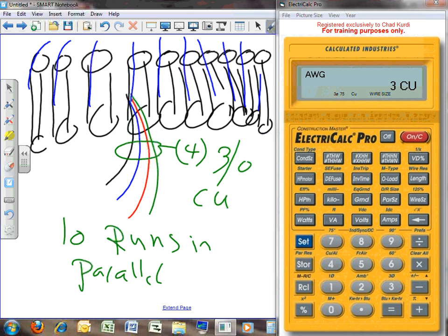One phase. All these phases, each one is landing on the same switch gear with lugs. Can you see how each phase is landing on one lug, the same phase? So you took one phase from every conduit and you land it on one lug inside that bar of a switch gear. Now imagine 4 of these: one for the red, one for the black, one for the blue, and one for the green, the neutral. And that's from this end. From the other end, I'm showing it from one end, the same thing, guys.